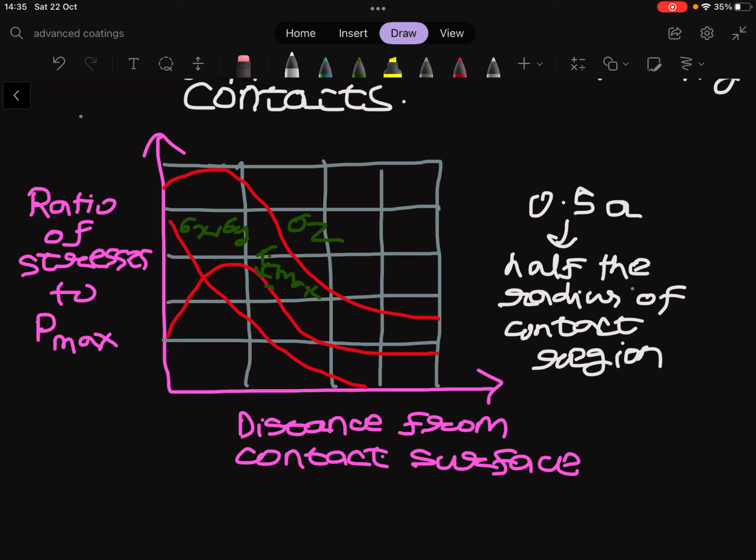So typically contact is through asperities. We should remember that Hertzian analysis holds in the elastic range. So if we extend this concept to a contact between two asperities, we are speaking of bodies in the range of some micrometers. So this depth is proportional to the size of the object, so it is very close to the contact area. Typically inside our coating, the applied coating can modify the stress distribution, thereby increasing the resistance of our surface materials. So we can remember this general conclusion to define the strategies to increase the load carrying capacity, which we are going to discuss in the next lecture.